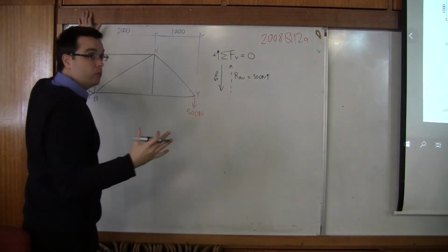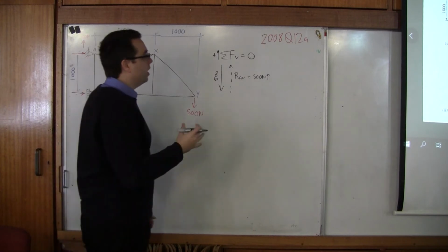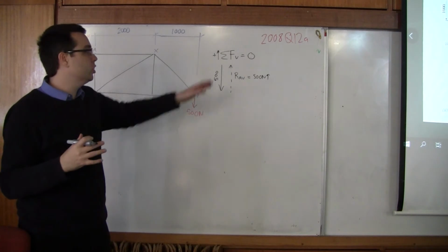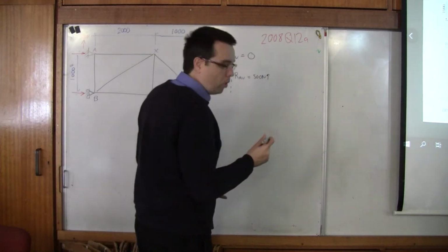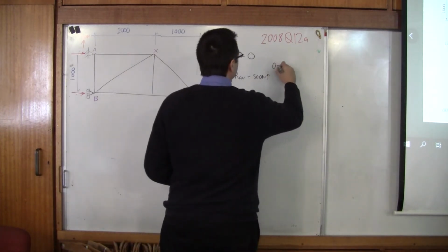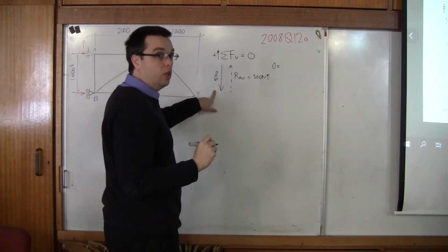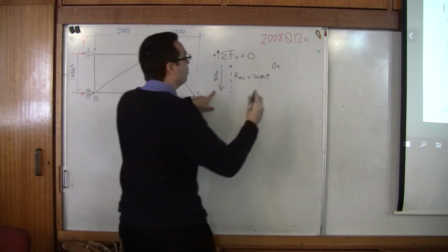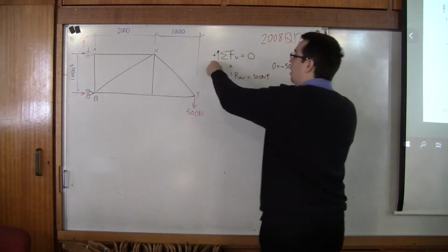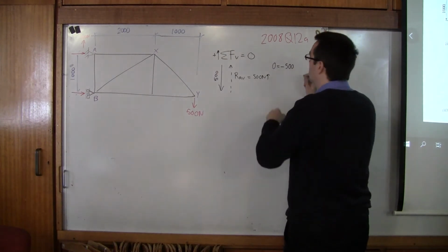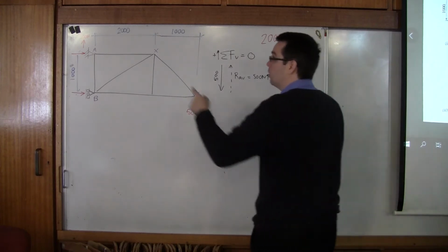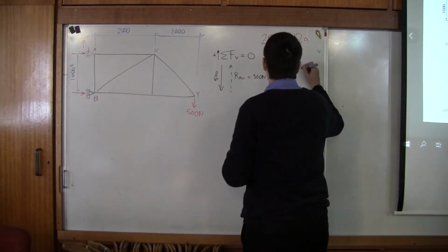There's no other alternative. Now, if I was going to write that mathematically, for the leftover force, I just draw a little diagram. But how we can write that is, I'm just going to write it to the side here. 0 equals, now I said 500, right? 500 is going down, so I have to write a minus sign because that's my assumption. Based on the convention that I've said positive is up, I'm going to write minus here, and then I'm going to say plus, because I'm assuming that this arrow is going to go up, plus RAV.